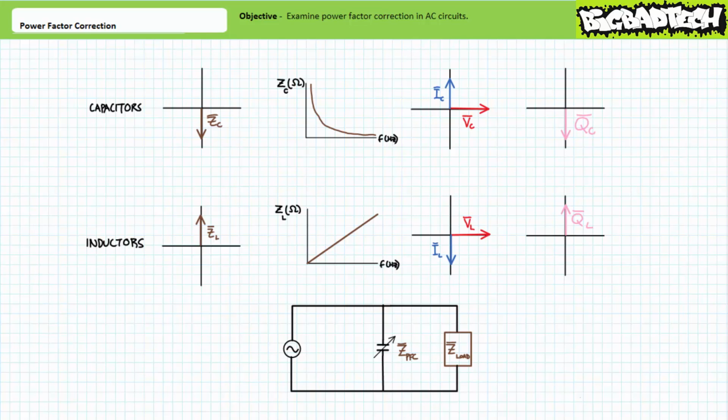Conceptually, you might think of a power factor corrected circuit in the following fashion. For a perfectly power factor corrected circuit, the moment the inductive portion of the load is building and sucking in current of a given magnitude, the power factor correcting capacitor is discharging that exact same amount of current. In this sense, the power factor correcting capacitor is dumping all its stored power into the inductive portion of the load just when it demands it.